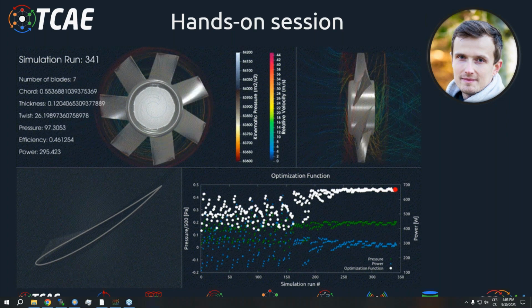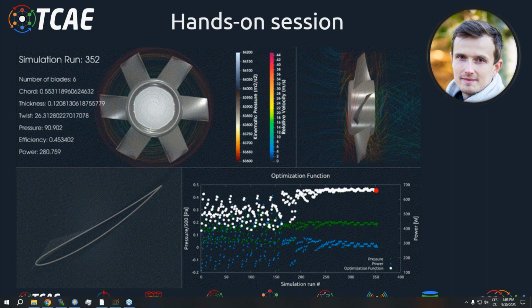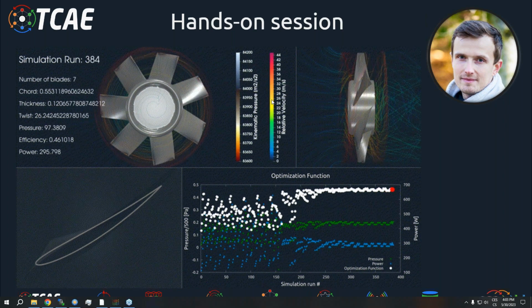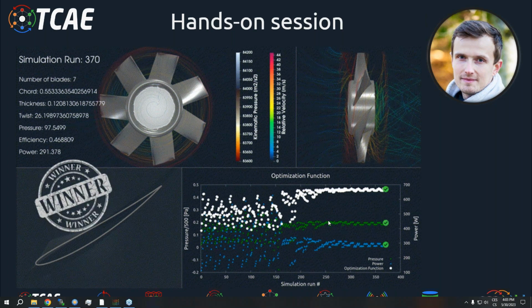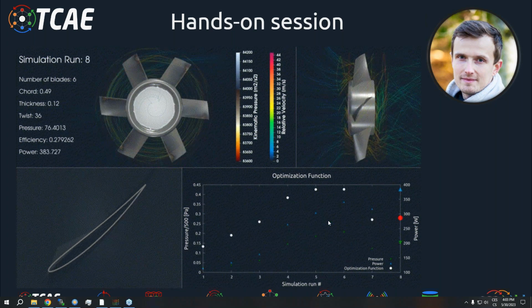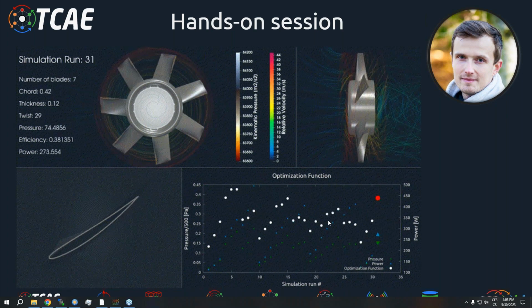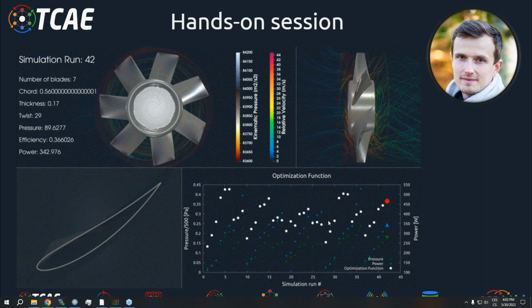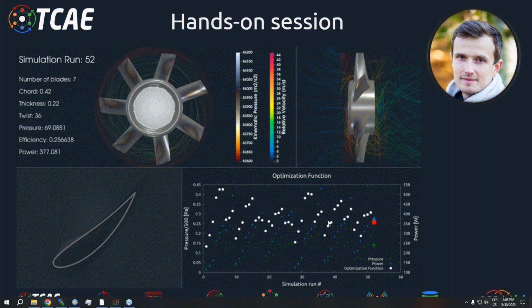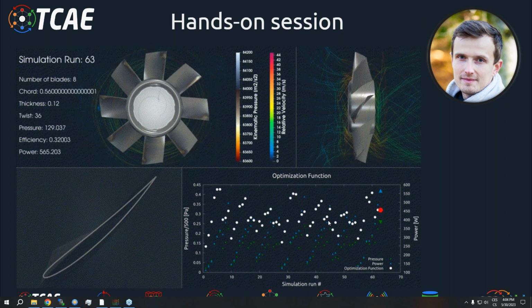May I interrupt you? It's the efficiency for the whole domain, including the chambers, which were part of the original design. So it's not the efficiency of just the inlet before the fan and the outlet in this shroud section, or casing, but for the whole domain, including the chambers. So it also depends on the losses which are gained in the chambers. I think the efficiency for the rotor alone will be much higher. Yeah, thank you, Radek. Could be the reason. Yeah, it's not very high. Okay.